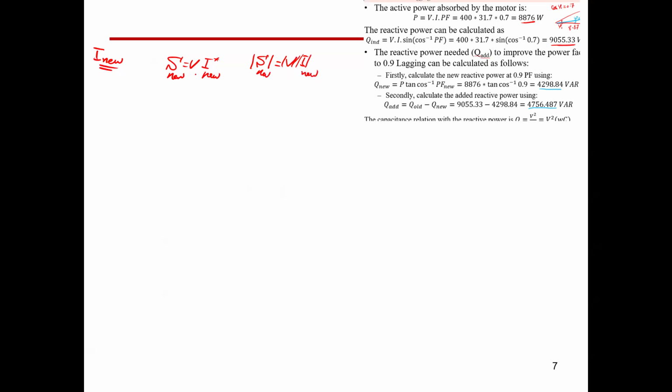The grid volt is going to be the same, or we can assume that volt is the same. Okay. Let me say it's not for undergrad to say if the volt is going to be the same or not, because injecting or changing the reactive power would improve the volt, but this is for the isolated systems. But this is another topic. We may discuss that in the synchronous generator when we discuss the dynamics of the synchronous generator.